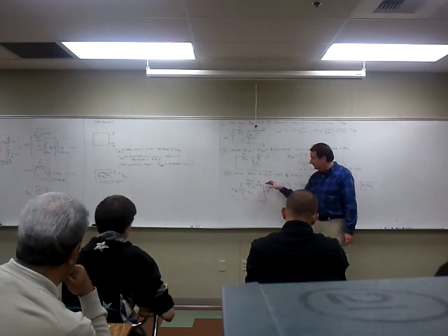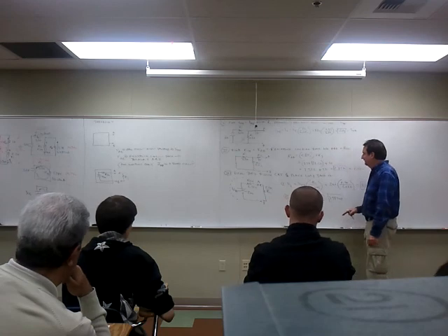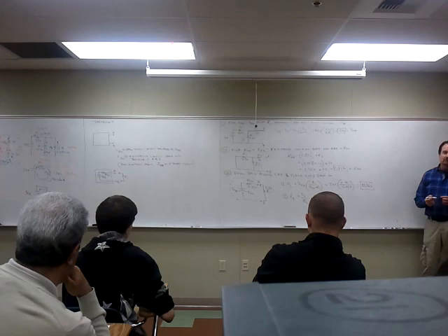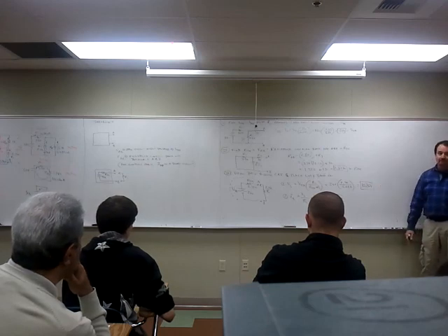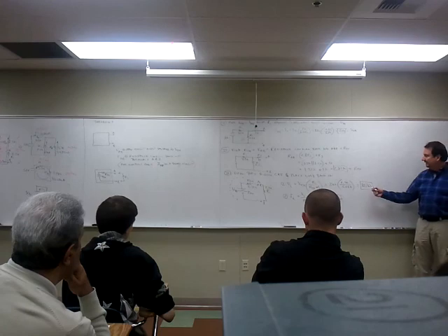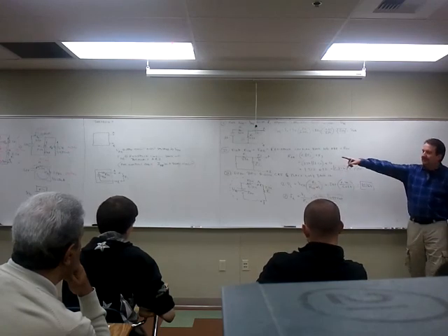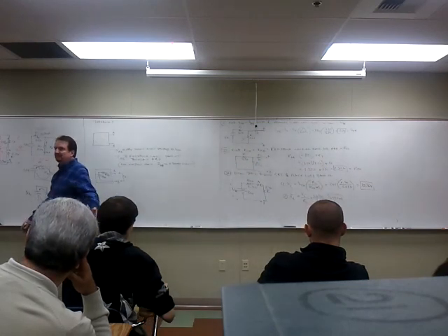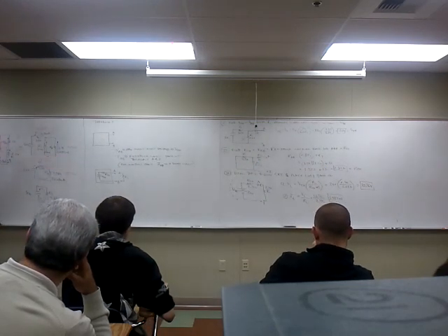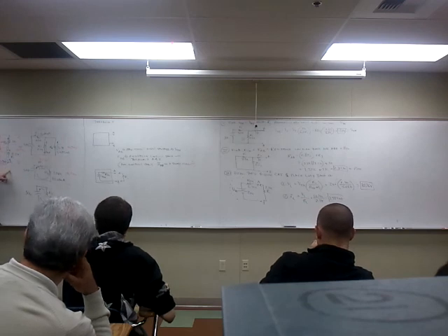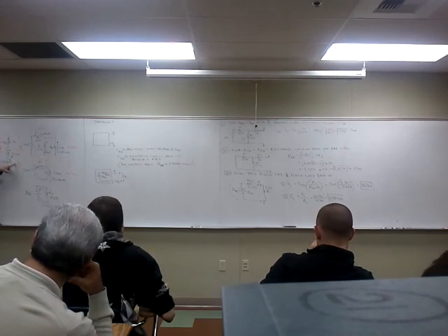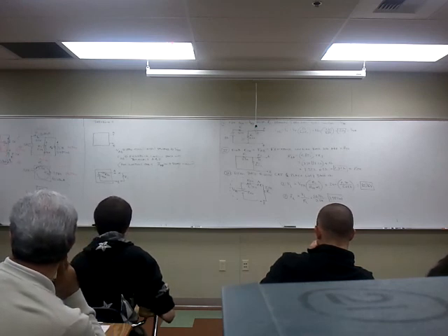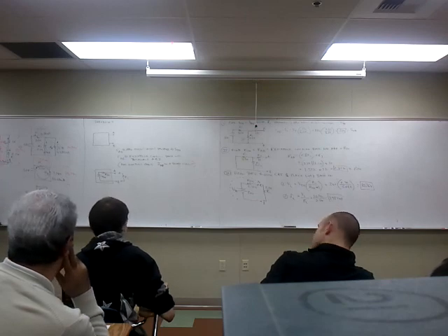Now what do you do with it? You draw the Thevenin equivalent circuit and throw the load back on and find the voltage drop across the load and the current through the load. That's a simple series circuit. You use series circuit techniques. I chose to use a voltage divider here, but you could use normal series techniques. And when we got these answers, didn't they match the answers in our original circuit? That's why I did the original circuit. Would it mean anything if I just did that and got answers? But you saw, using normal series-parallel, that we found the voltage here and the current through this load resistor, and it did in fact match our result using Thevenin.